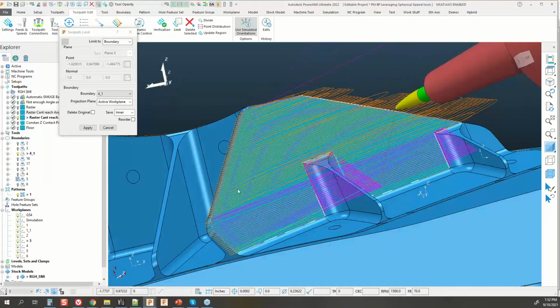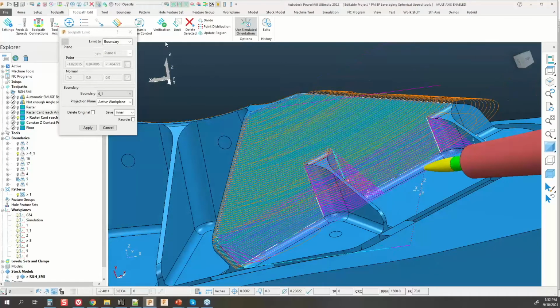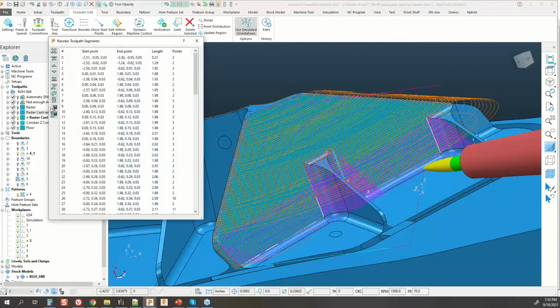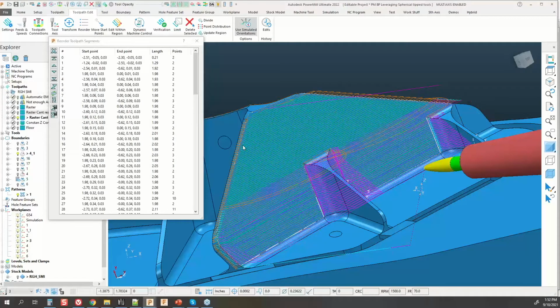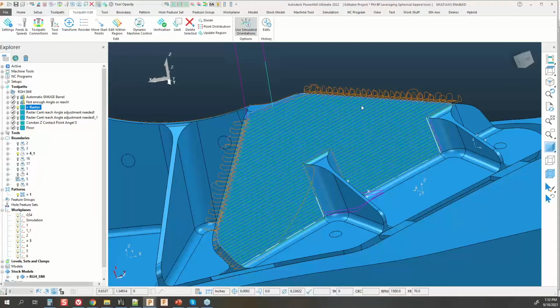Now I've got leads and links here, and you can see this is going one direction at this point, so it's kind of just looping around on that toolpath itself. So in order to get rid of those loops again and make it back and forth, that's where I'd come in, zigzag it, and there would be reordering involved here. It's not always going to be as clean as we'd like it to be, but eventually with the edit toolpaths, you can get to the very clean toolpath where you have back and forth method working out that distance.